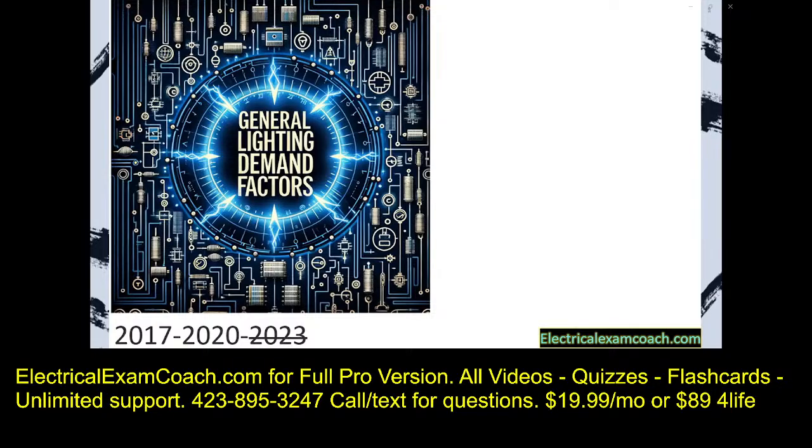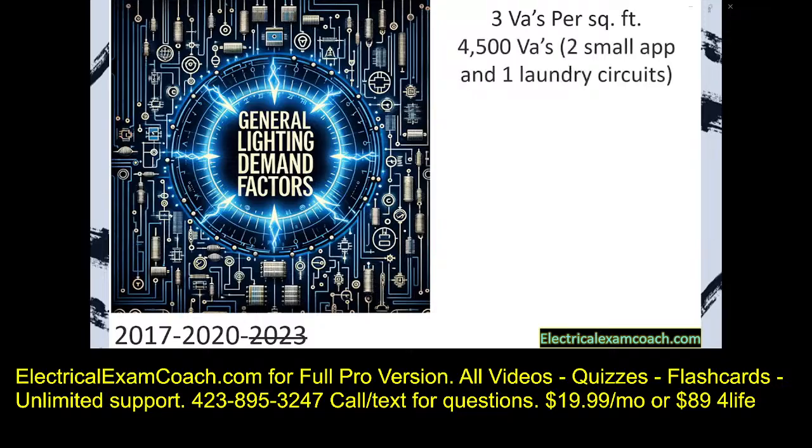Now we're going to learn how to apply the demand factor to the general lighting load. At the beginning of the program, we learned that it was 3 VAs per square foot, and we had to add on the 4,500 VAs for our 2 small appliance and 1 laundry circuit. At the beginning of the program, I did not teach you about the demand factor for this because it's kind of complicated at face value, especially if you don't know what a demand factor is. But now that we're this far in the program and you are very familiar with using demand factors, I'm going to teach it to you now.